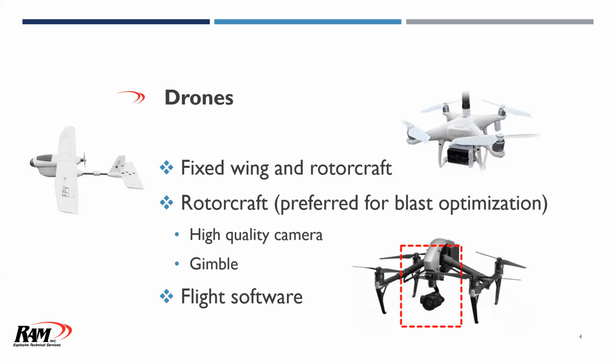And most drones, as they're purchased off the shelf, come with just kind of a minimal package so that it can be hand flown. In some cases where maybe you're doing some larger scale mapping, things along this line, the flight software is really beneficial to help out in those types of applications. So that may be something that you'd want to look at, depending, again, what is your goal in this and what type of flights are you planning to do, especially if we're looking at kind of large scale mapping, ortho, to generate an ortho map. That's where the flight software can come in pretty handy.